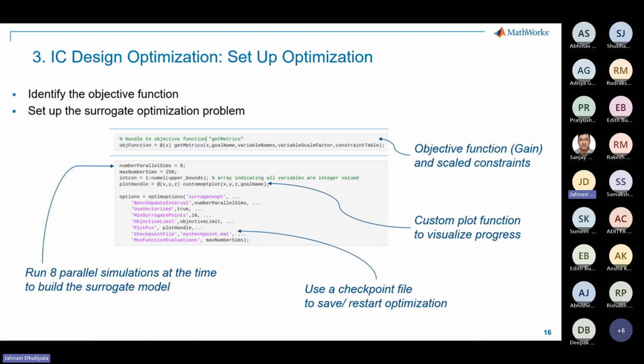So we select the surrogate optimization algorithm, a global optimization tool, for its known robustness in handling non-continuous problems. If you see here, when we are trying to optimize the transistor sizes, definitely it won't be a continuous one. It will definitely be a non-continuous problem. It might keep on changing. So these non-linearities, what we call non-continuous problems, need to be considered. And this global optimization or the surrogate optimization is the best one, which can be used to provide us efficient results.